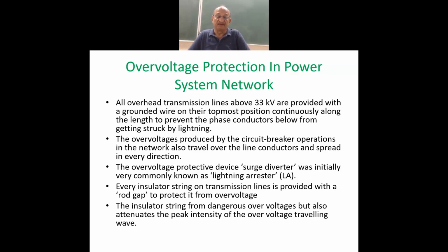But when the transmission voltages increased beyond the 400 kV level, the magnitude of the switching impulse voltage, the SIL, increased with respect to the rated voltage, because it is proportional to the rated voltage of the system.